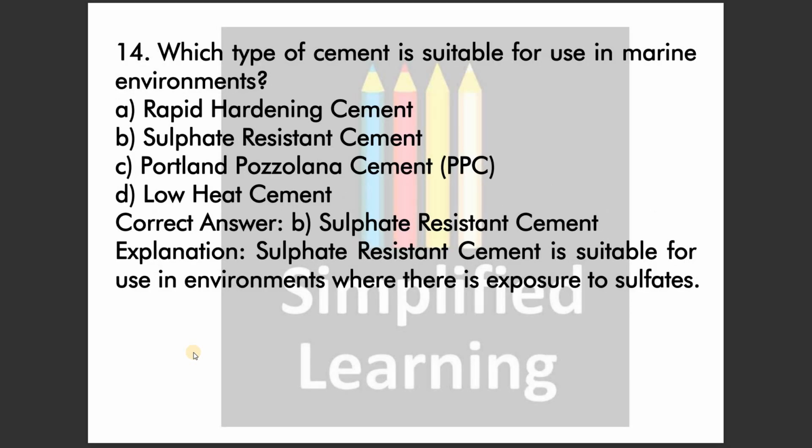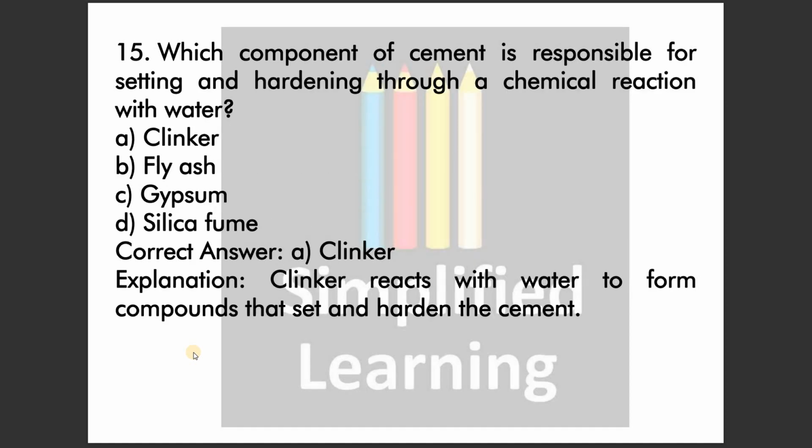Then, which kind of cement is suitable for use in a marine environment? See, the answer is sulphate resistant cement. Wherever chemicals and salinity are exposed to the structure, we are going to use sulphate resistant cement.